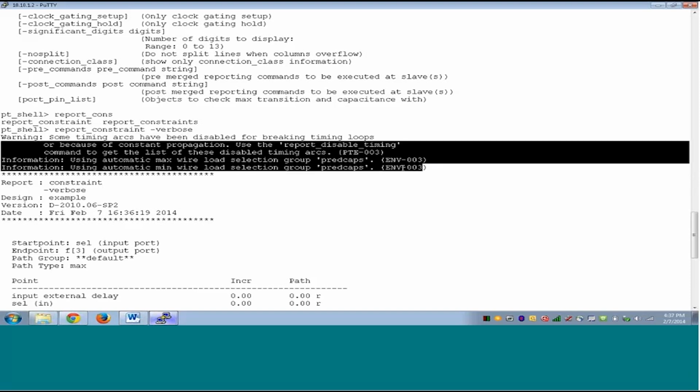But for big designs, a delay calculation takes a lot of time, so you have to be careful while changing constraints for a big design and for a big chip, and you should be prepared to wait that long, right? So for the chips I work on, the update_timing usually takes somewhere around 3 to 4 hours easily. So we make sure that we only do update_timing after we are very sure that all of the constraint changes have been ported in.